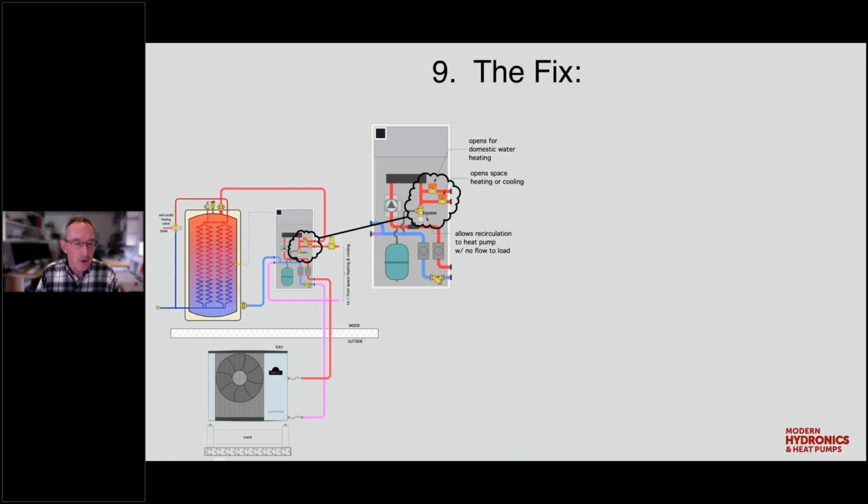Well, we still have to have flow through the heat pump while we're waiting for the temperature of the fluid to adjust. That's where the bypass valve comes in. This is a pressure activated bypass. The flow would basically come in here. Since these valves are closed, it would go through the bypass and basically right back out to the heat pump.